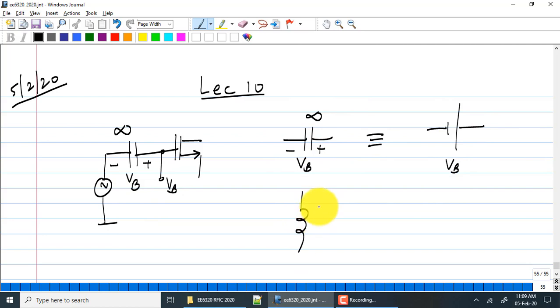Similarly, we also saw that if you establish a current I0 through an infinite inductor, this is exactly the same as having a current source of value I0. Okay, so what you could do, you could choose a large enough inductor such that at the frequency of interest, the impedance is so large that no signal current flows through it, and all of the current would flow through the load. Such an inductor is called an RF choke.